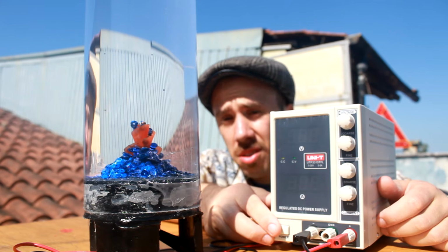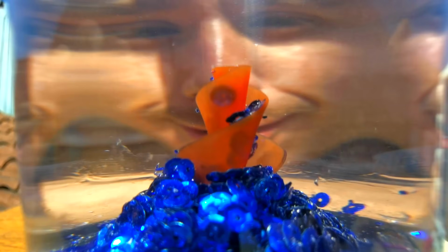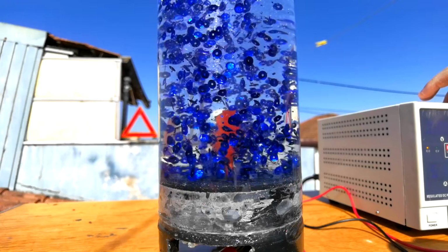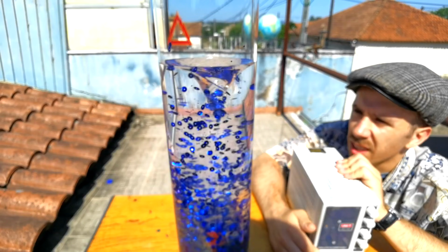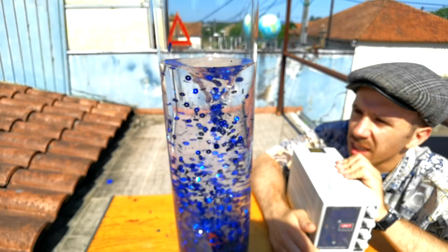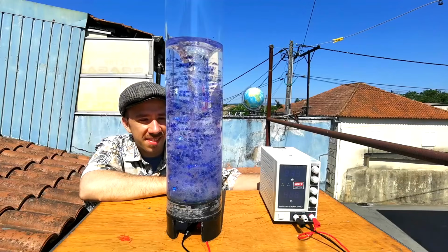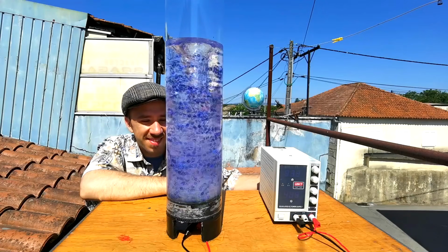In 3, 2, 1. Even when rotating it in the opposite direction, the water is still displaced outward, but this time in a positive angle. The result is mostly the same because we still get a recirculating flow that starts at the bottom, is pushed to the top, and because of the low pressure at the center, ends up flowing into the impeller again, which means that in the end, the vortex is still generated.